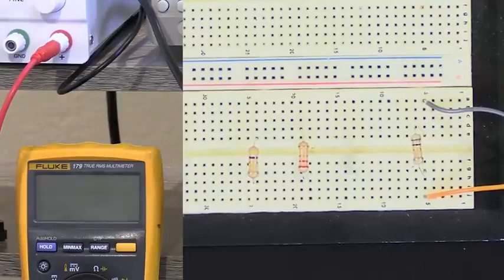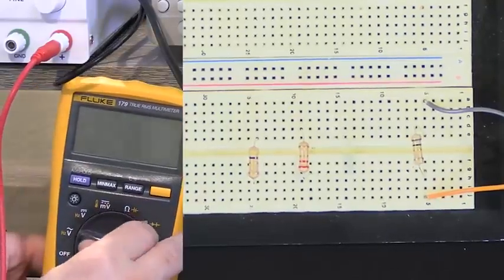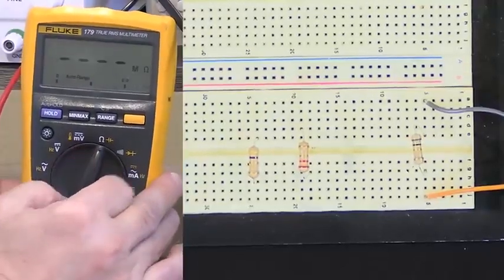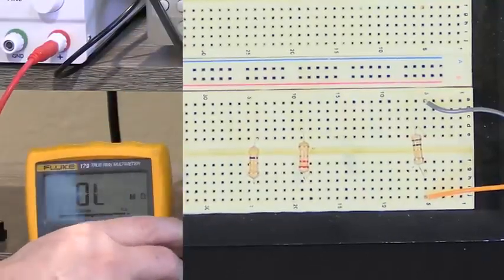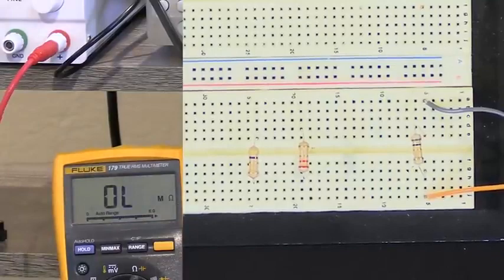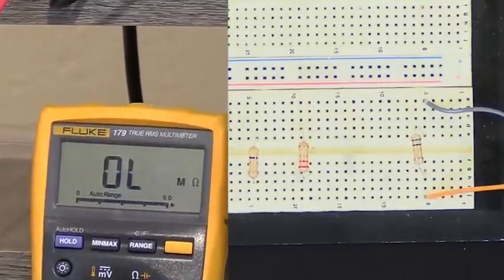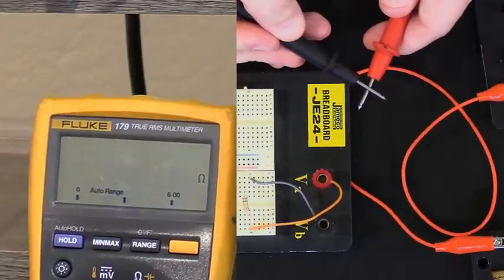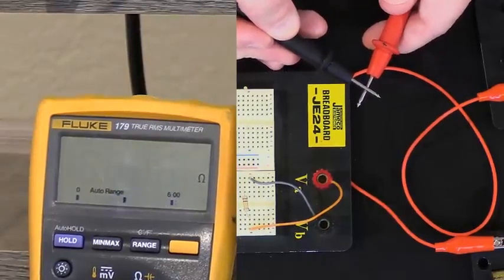I have over here a voltmeter, and I'll show you in a separate lesson exactly how to do that as well. All I'm going to do is turn this voltmeter to the ohm position. Let me see if I can get it where you can see it. I'm going to put it right back down here so the camera can see it. And hopefully, I can move these wires out of the way. You will be able to read that. And right now it's measuring nothing. If I touch the two leads together, and it's not measuring any resistance, you can see on that display it's bouncing between 0 and very, very low.